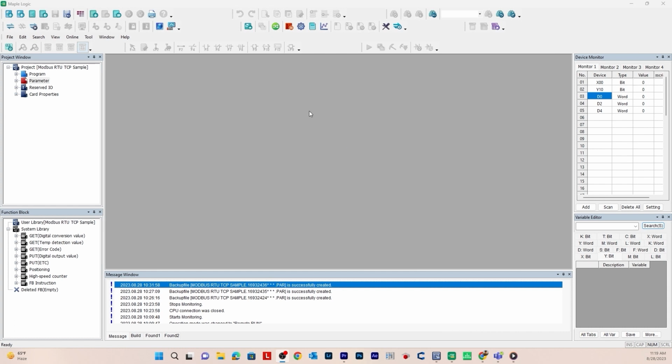In this video, I'm going to cover Modbus RTU and TCP configuration between a Maple PLC and a CMT 3102X HMI, the PLC as the slave and the HMI as the master device. I'll be configuring the PLC in MapleLogic and the CMT device in EBPro software, but you could connect to any device that has Modbus capabilities. First, I will be covering Modbus RTU configuration.